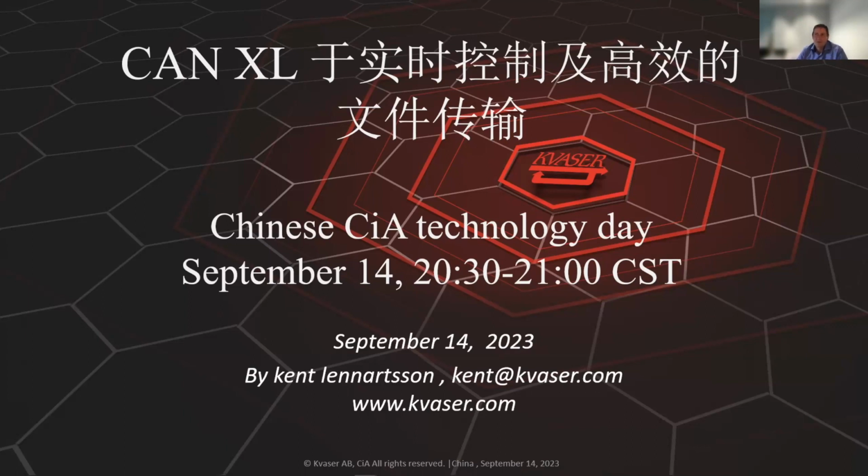So if you really want to go for these 20 Mbit, as Kent has presented, you need the dedicated CAN-XL transceiver. And Kent, I think from NXP and Infineon, there is something in the pipeline. At least from NXP, I have seen some prototypes at the Embedded World fair. Infineon maybe a little bit later. So at the end of the year or beginning of next year, I think there will be something, isn't it? Correct.